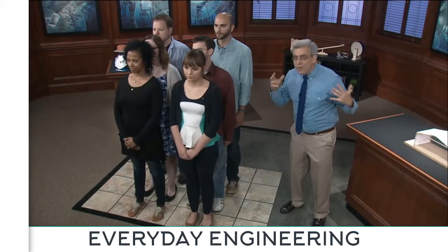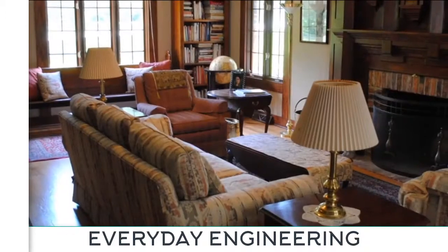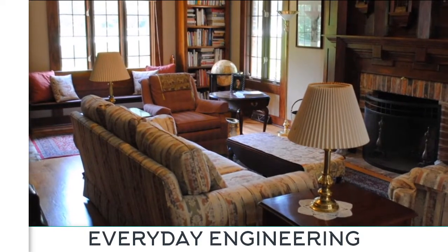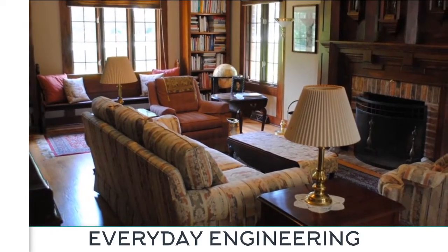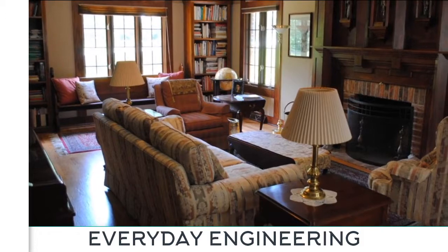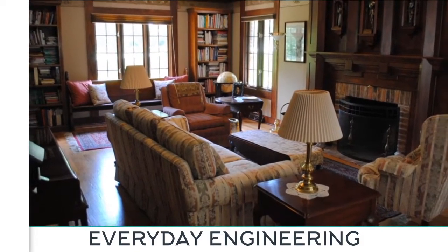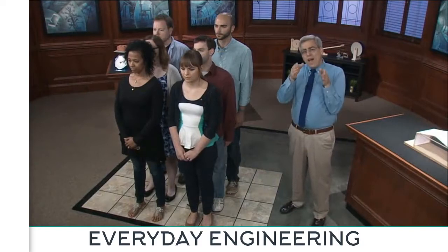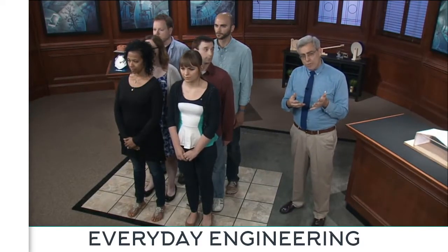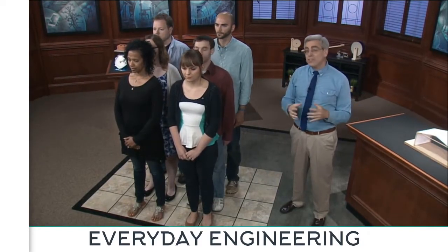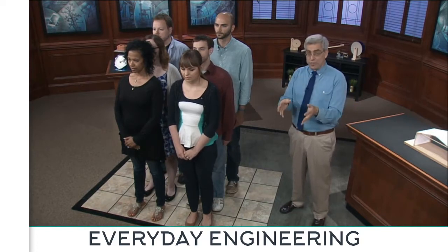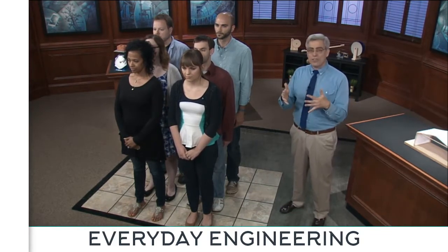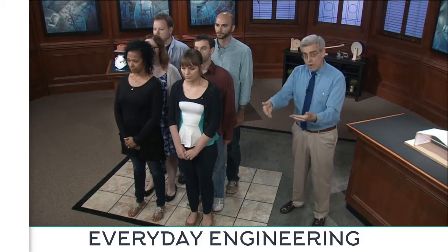But this simply couldn't happen, in part because a substantial portion of my living room floor space is already occupied by furniture, but also because there's simply no circumstance under which 200 people would be in my living room. Thus, even though a live load of 85 pounds per square foot is physically possible, it's so unlikely to occur in a residential space that the code allows us to design for a much lower loading.